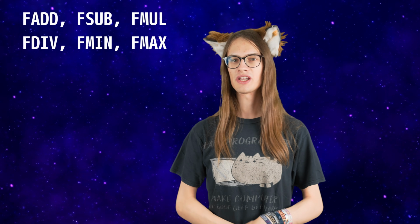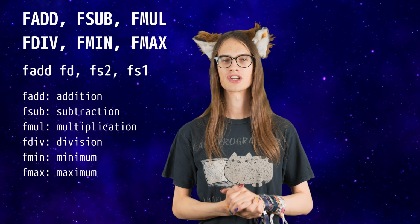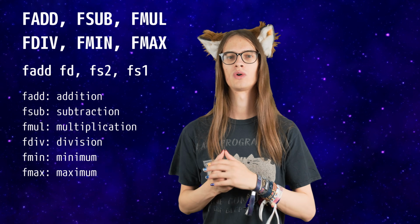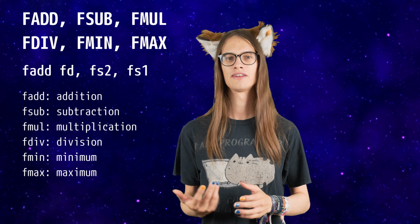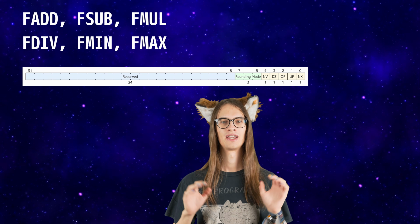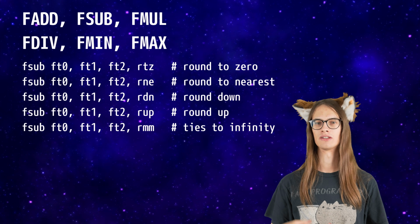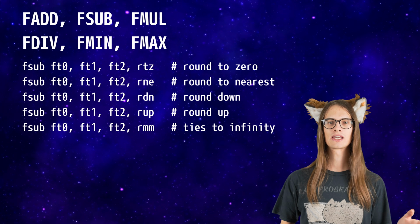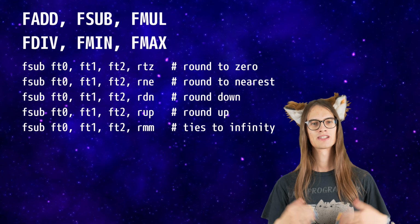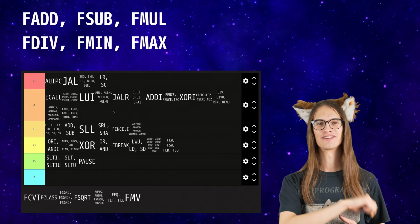Basic floating point operations are as you would expect them, and they're very similar to integer operations in all regards. There are no exceptions when we divide by 0 or otherwise produce a NaN. There is just a flag set in the floating point exception CSR. Very interesting is that the rounding mode can be set directly in almost every instruction, and we can also set it in a CSR as a dynamic rounding mode. Some of these rounding modes are not even supported by x86. Definite A tier for the design here.